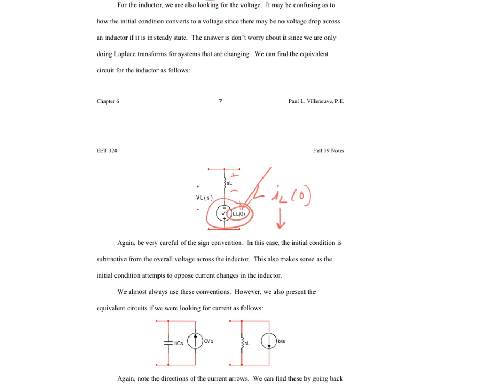And here's the advantage. Do you remember how we had to do t equals 0 minus, t equals 0 plus, and t equals infinity? When we did those analyses, what did we have to do every time we did a t of 0 minus, t of 0 plus, t of infinity? What was the first thing we did? We redrew the circuit, right? Guess what? You draw it once in the Laplace. You don't have to redraw. Okay? You will need to maybe perhaps draw it over here so you can get the initial condition calculation. But the t of 0 plus and the t of infinity from a circuit's perspective looks exactly the same.